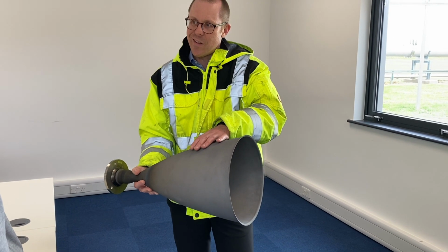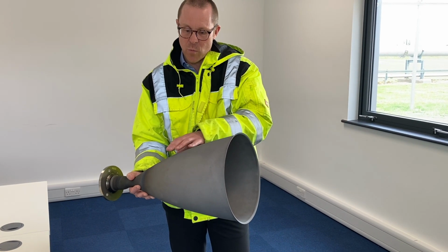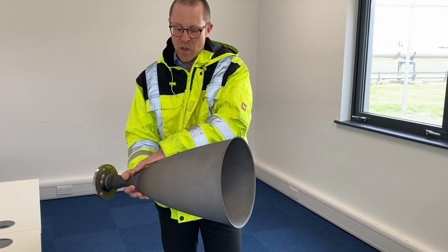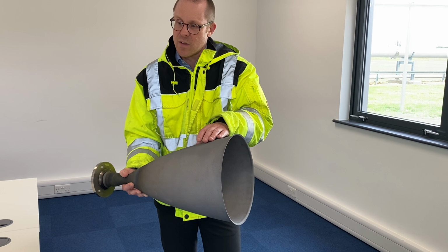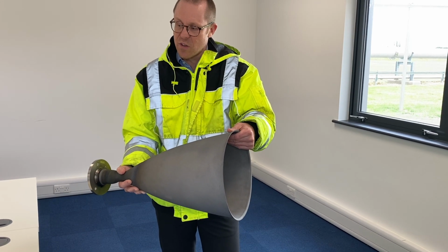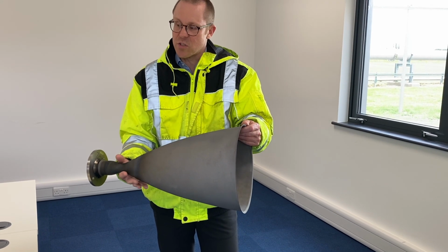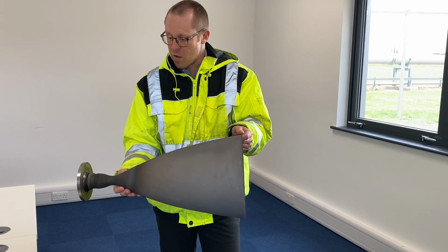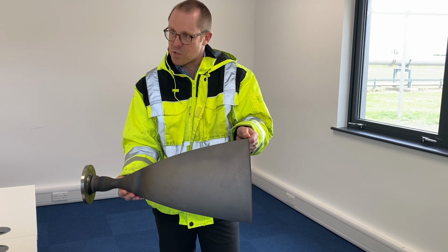An idealized, optimized rocket engine is one where we get as much velocity out the back end of this engine as possible, and we do so by expanding. And that's the reason why there's an expansion chamber on it, and all high performance space engines follow this trend of a big expansion cone on the business end, which is the combustion chamber portion.